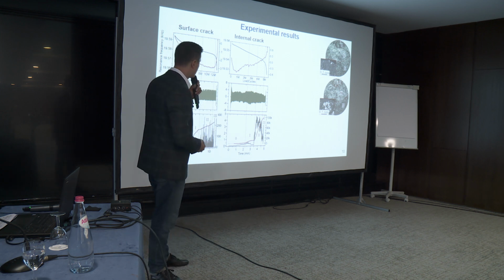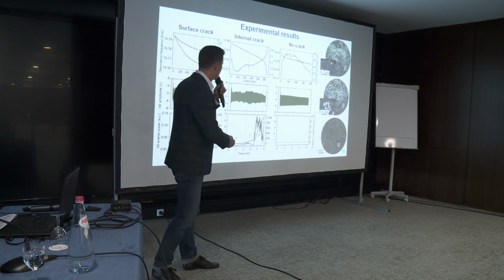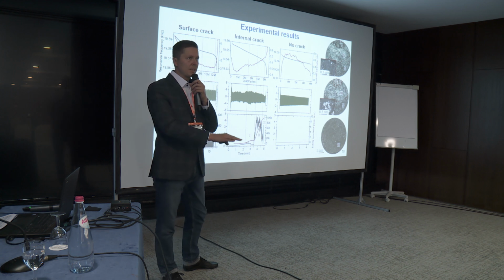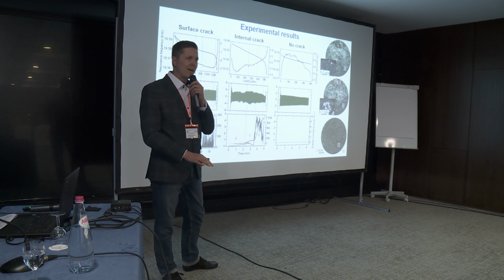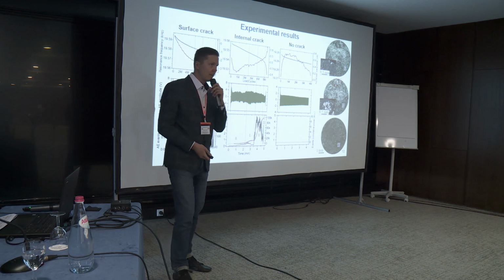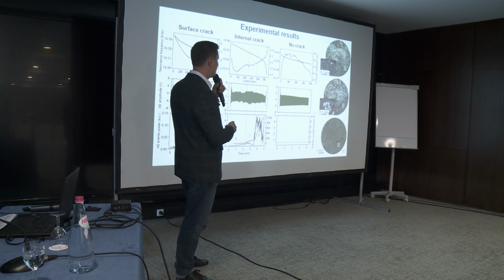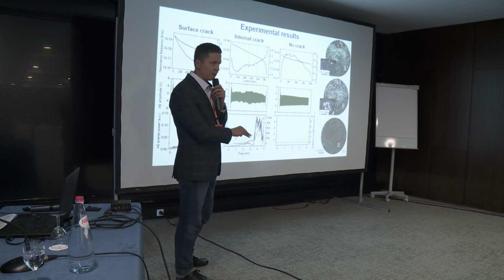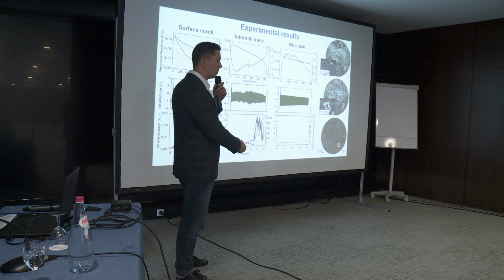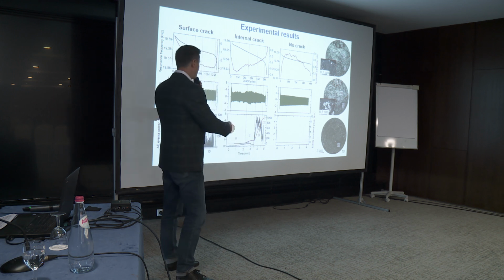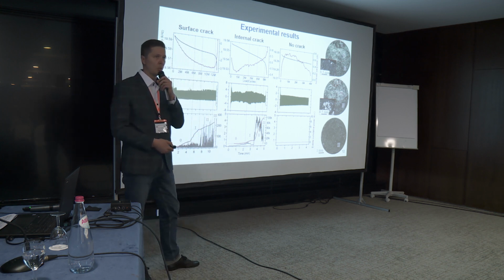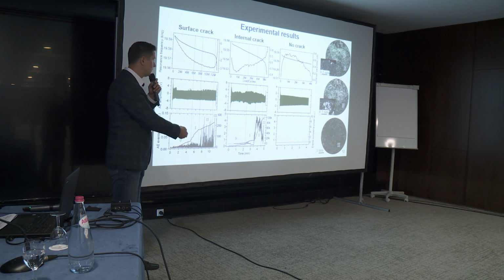Before I go to the next step, maybe after this. This is the reference state. After the fatigue testing is done, we need to break the specimen manually by cooling it down in liquid nitrogen, and then we break it. With the reference state, we knew that there should be no crack, so we stopped the experiment preliminarily. We broke it, and we could see no fatigue crack at all. And as you see, again, the acoustic emission results correlate perfectly with what is going on. So we have no activity.